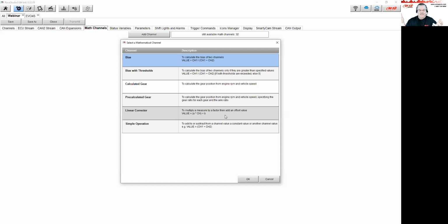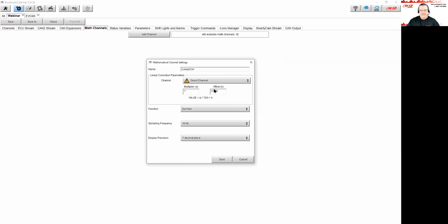It's only showing like 85%, and you really want 100% because you're doing some downstream math with that, and you want it to show true actual values. You can come in here, click on that and add a multiplier. So it takes the 0% and multiplies it by 1.2, and it also takes the 85% and multiplies it times 1.2 or 1.15, and so you end up getting a nice linear corrector.